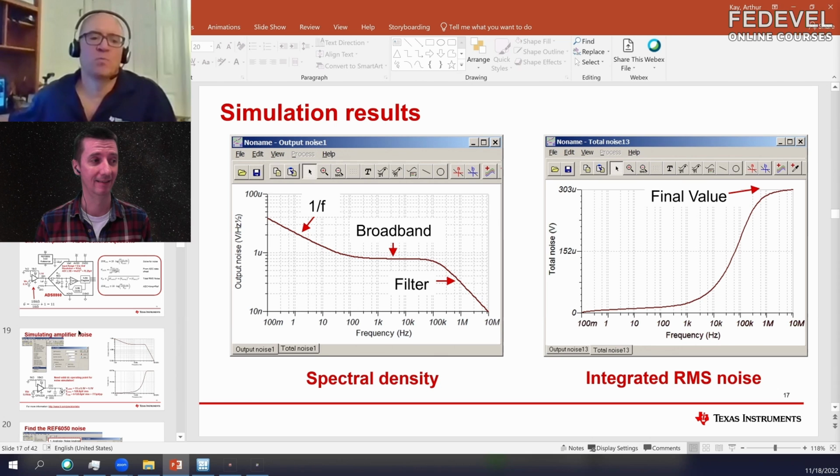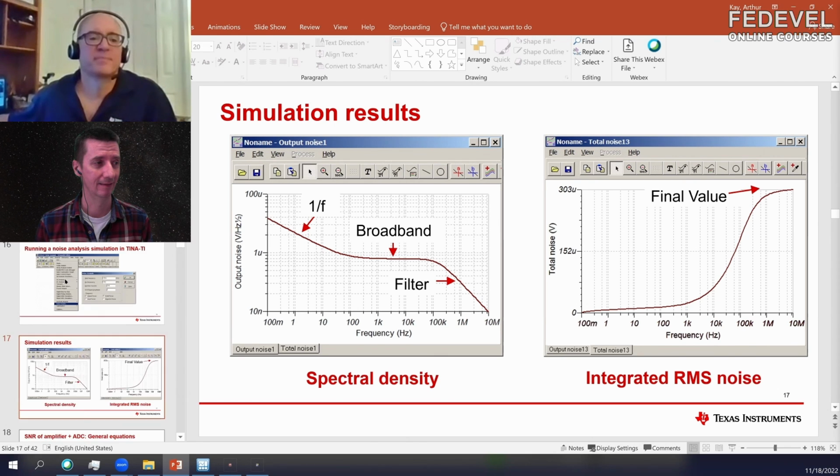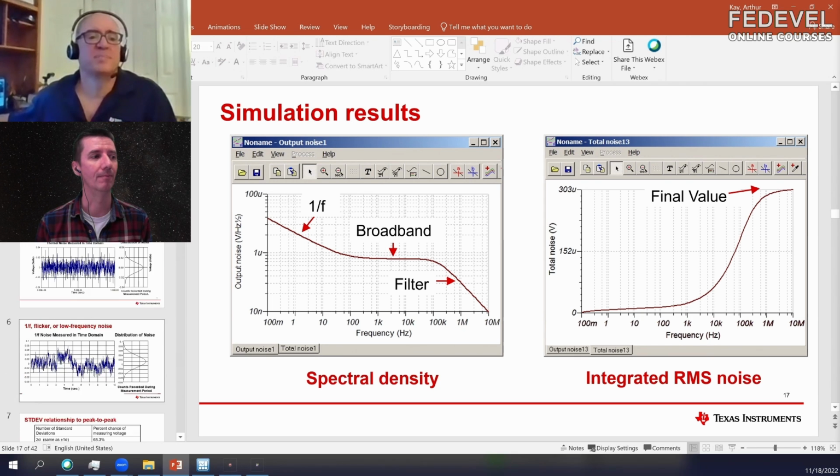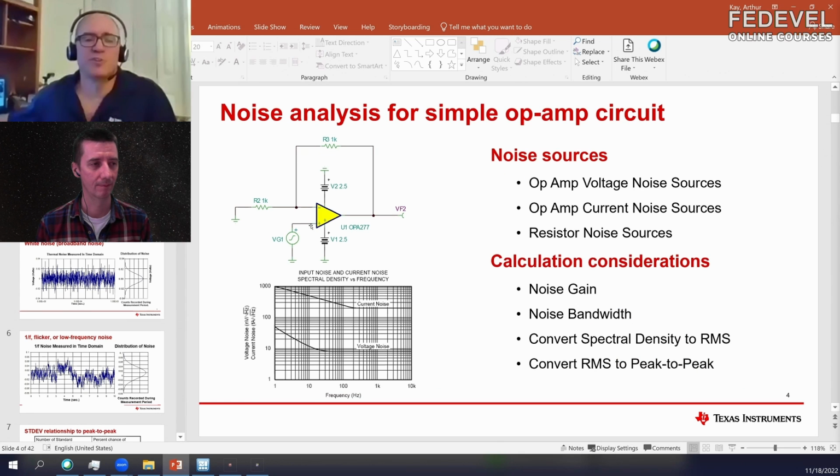If you think about it, the noise of an amplifier is really the offset shifting with time. So it's the input signal here shifting with time. And if you calibrate that offset continuously, with some kind of switching circuit on the input of the amplifier, you essentially measure and cancel that offset change over time. It eliminates the temperature drift of the offset, but it also gets rid of this 1/f region. It flattens it out. I had no idea.